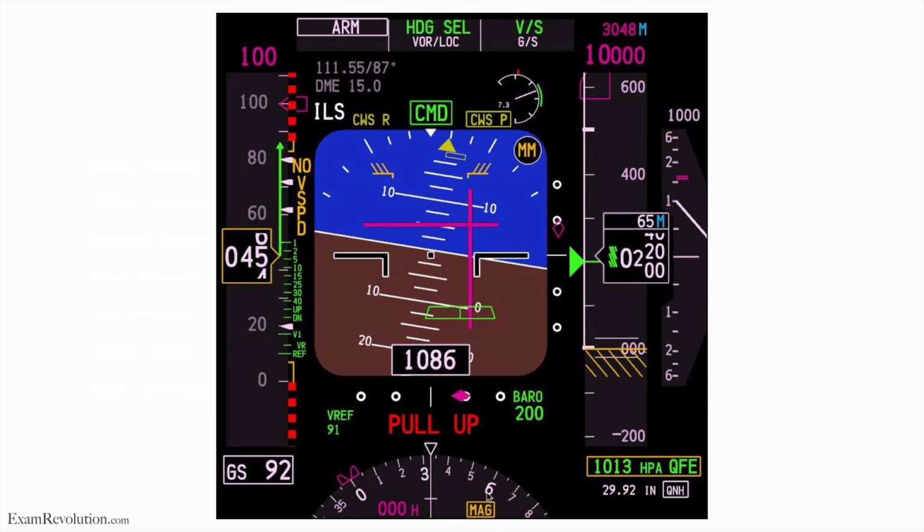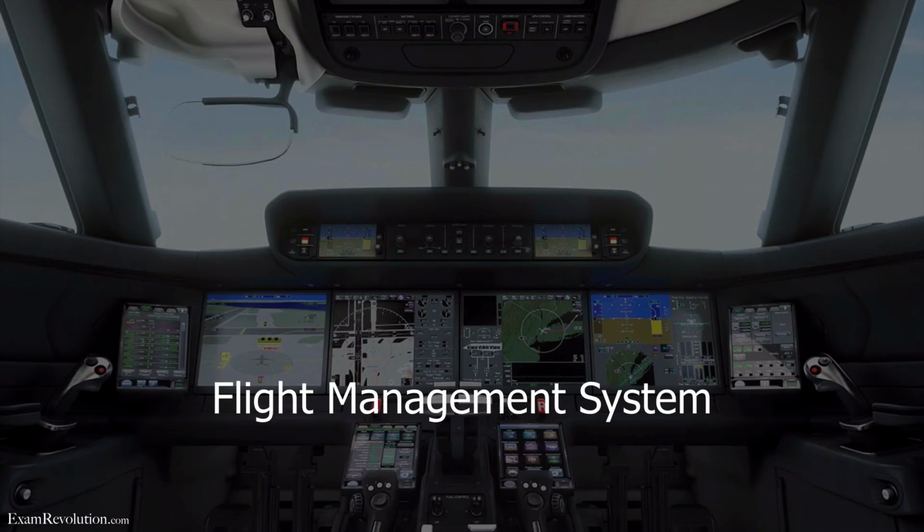And then you can see caution as well, right? It says your MAG. I'm not 100% sure, but this might be displayed when there is an issue between the magnetic heading of this PFD compared to the co-pilot's PFD. Or if this is the co-pilot's PFD, there might be an issue, you know, with a heading comparison between this one and the captain's PFD. That's why it might show you a MAG there. And the reason for that is it picks up the difference, right? And obviously you can see it is amber. It's orange, so that's like a caution message.